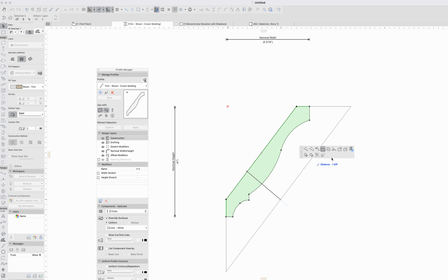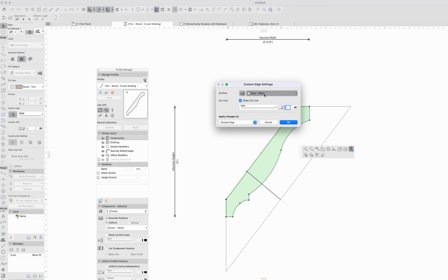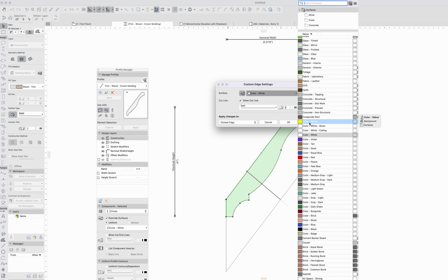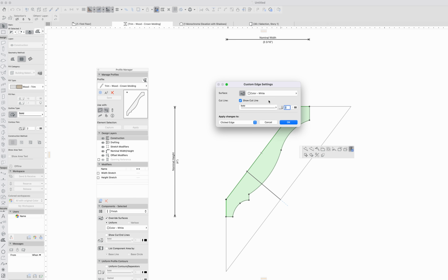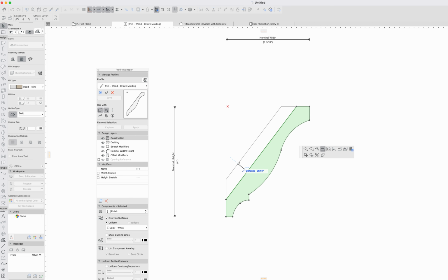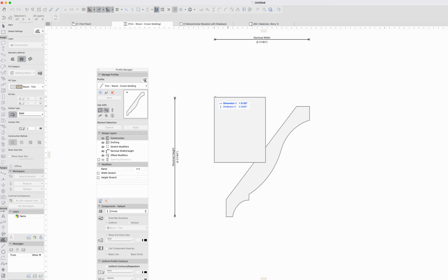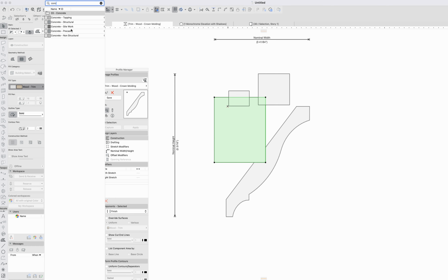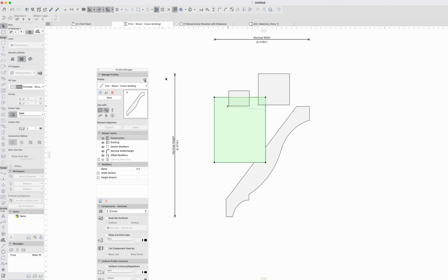If we were to click on this fill and maybe edit this edge, I can see that surfaces are a sub-attribute as an override to the extrusions. There is a line type sub-attribute, and there is a pen type sub-attribute that can be applied to this. So we have building materials, we have pens, we have lines, and we have surfaces all applied to this complex profile. And quite literally, whatever you can draft out becomes that profile extrusion. There's no limit to how many different building materials you can include in here. Whatever you need to draft out can be extruded.